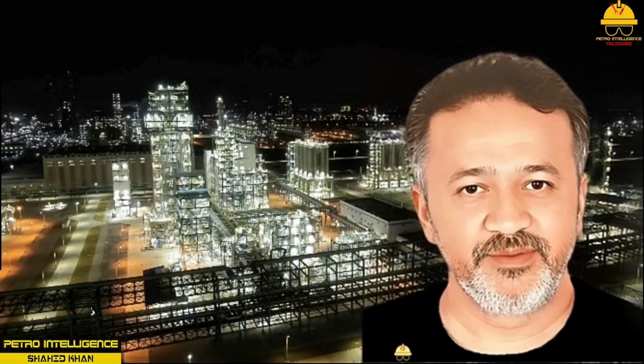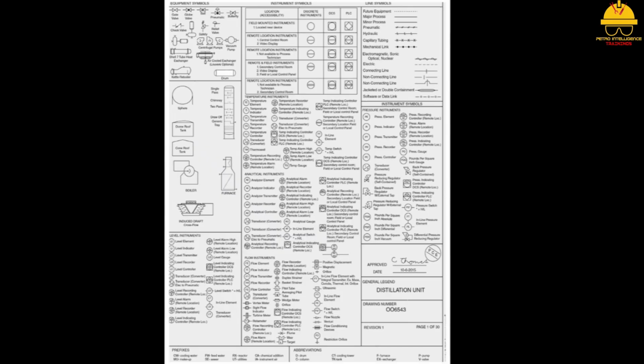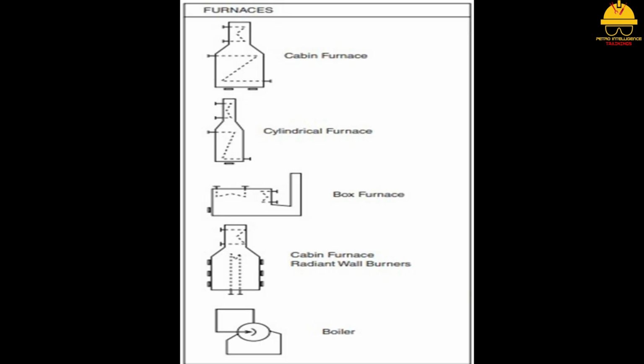On a typical P&ID, distillation columns, reactors, boilers, and furnaces will be drawn as they visually appear in the plant. The standard symbols file for these devices can be found in this picture. If a proprietary process includes several types of equipment not typically found on a standard symbol file, the designer will draw the device as it visually appears in the unit. This picture illustrates standard symbols used for boilers and furnaces.